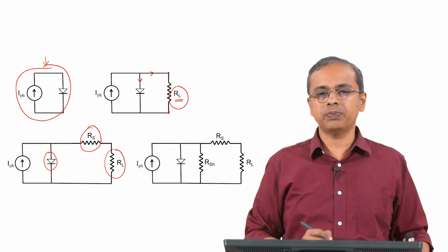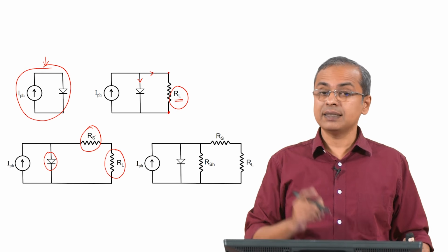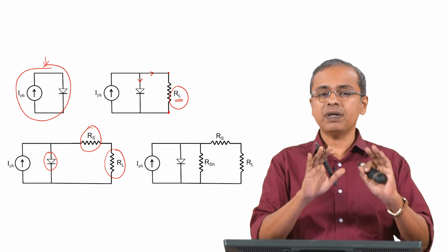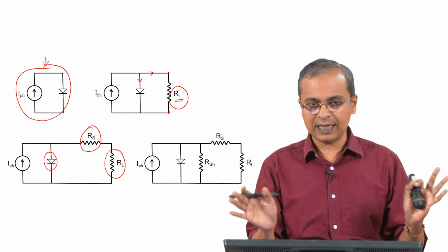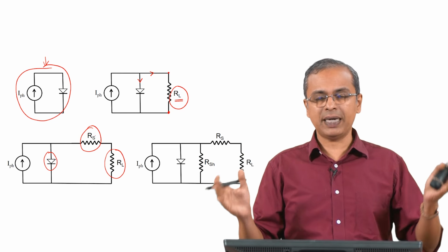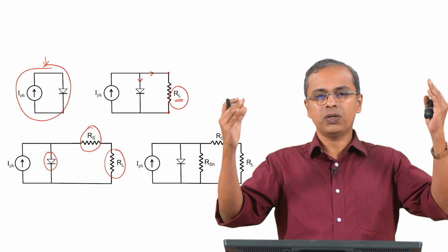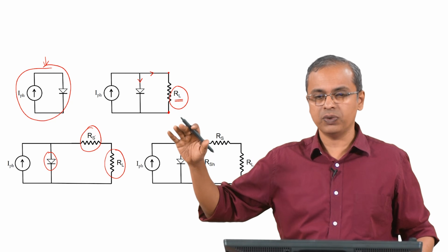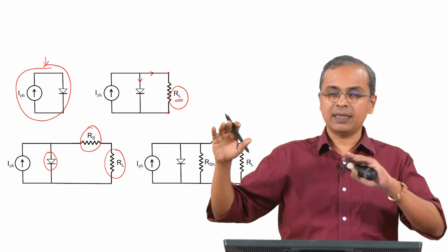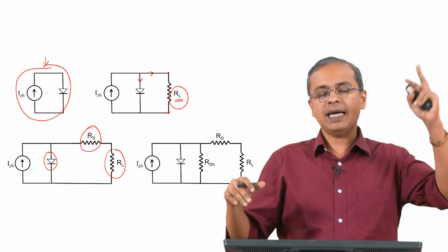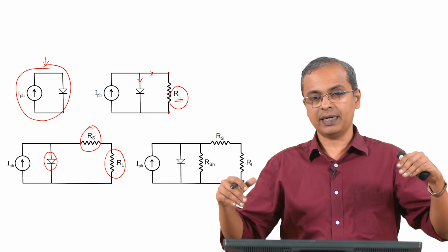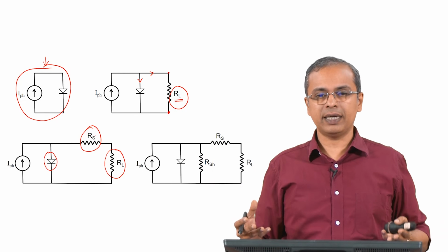The one other aspect that we have not accounted for here is that recombination that I spoke to you about earlier. Okay, so that recombination is even without this forward bias aspect of it, that does not involve any biasing aspect of it. It simply means you created electron and hole even before, let us say, the electron could go off to the n side and the hole could go off to the p side. It might get annihilated internally itself. On the p side itself they may get annihilated, on the n side itself they may get annihilated, but it is all got to do with the same solar energy that came in.